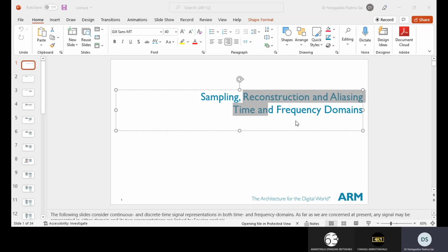Generally, the switching function may be an impulse or a pulse. Afterwards you get a continuous signal only, so you pass it through sample and hold, which holds the same value. Afterwards, that signal we call discrete. If you want to transmit that discrete signal, we do coding. Suppose after quantization I got 5. Instead of transmitting 5, I transmit 101. You already studied this in your communications course. Quickly I will run through it.